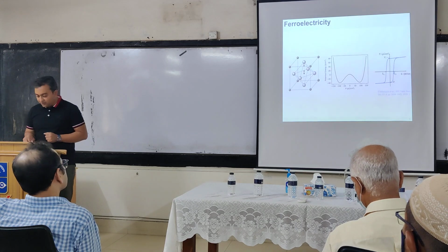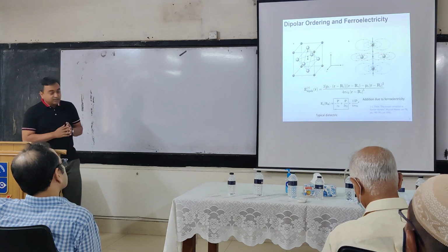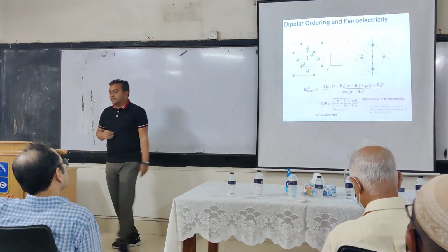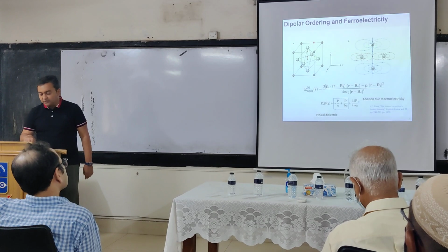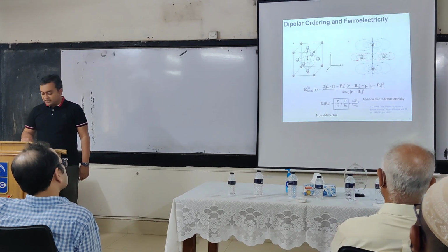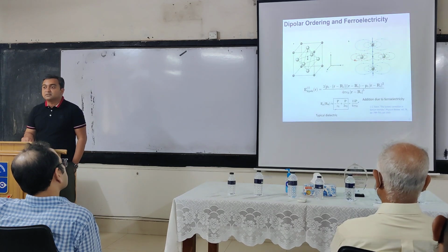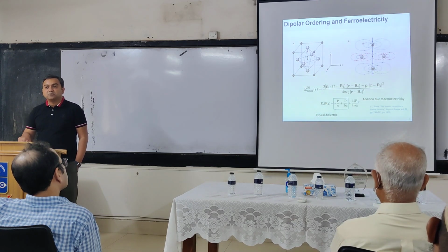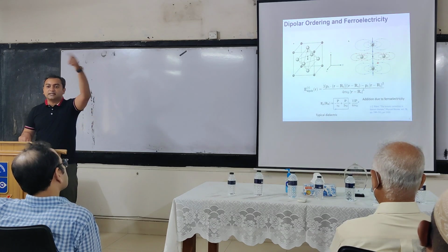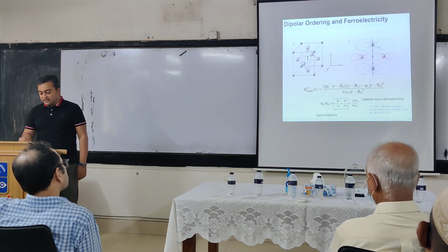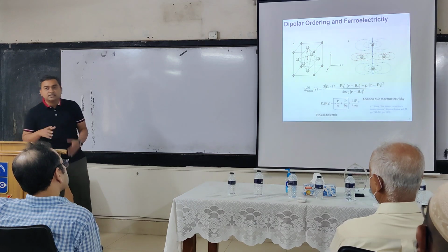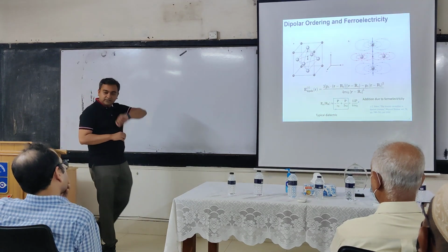Okay. All right. So let's look at it a little bit more deeply. So I just showed one unit cell, right? But a material is not made of one unit cell, it has many unit cells. So let's think about it as many unit cells. And each unit cell, we just agreed that there is a polarization. If there is a polarization, what happens? There is an electric field. If you have charge, field lines come out. So that means that these many unit cells, they all see each other because they are seeing an electric field coming out.